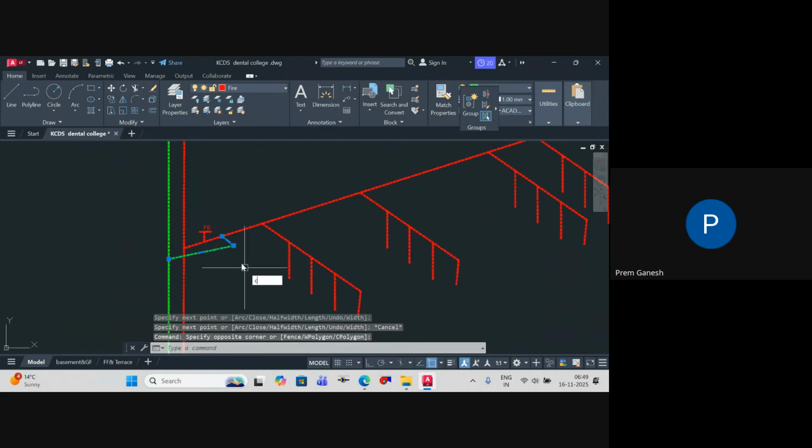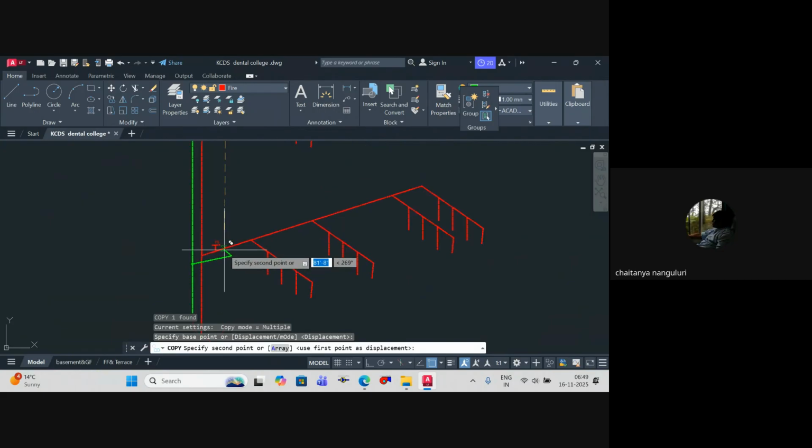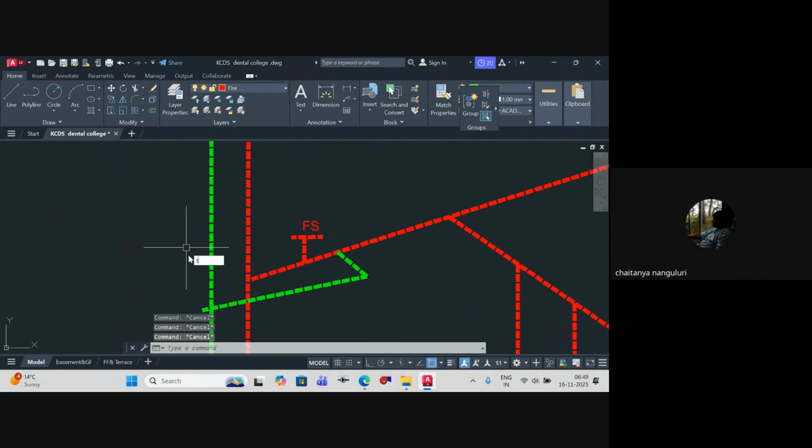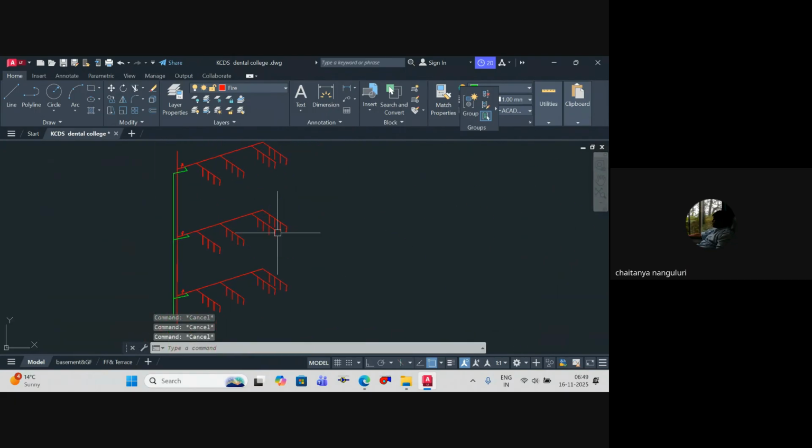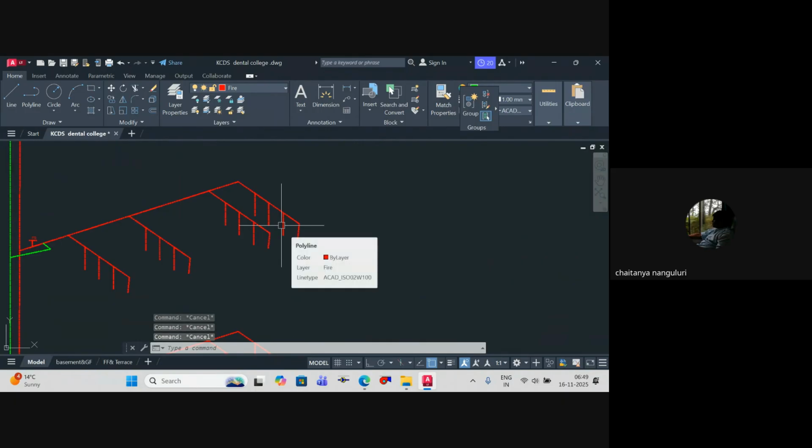What's the purpose of this drain point, sir? I'll tell you. Okay, two things. The reason why you require a drain. First and foremost, let's say a sprinkler got broken. It could be an accident or it could be because of fire. You agree?